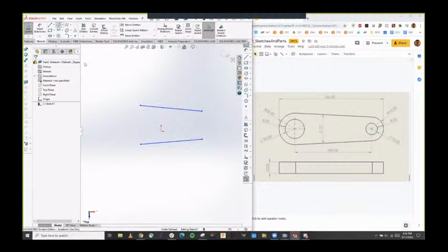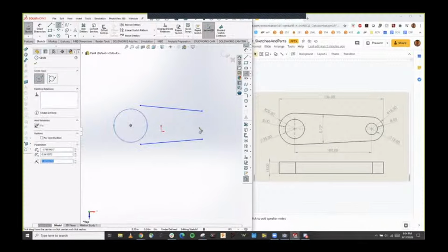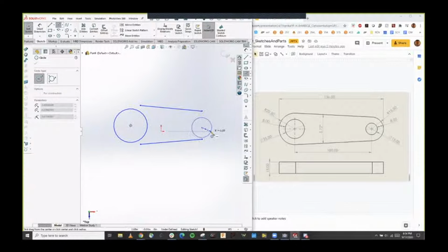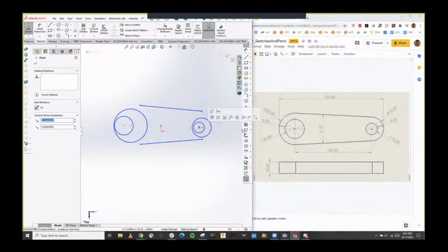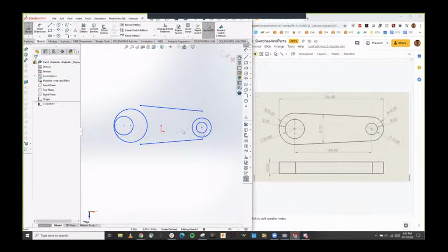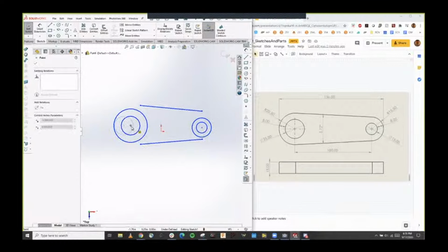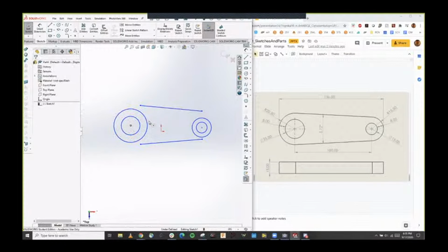Four circles, you say? Okay, we can try that. So I've generally got four circles. So we do have all the parts here. So I think what it looks like here is that these two circles, that sounded like a good suggestion. So I'll put these two to be coincident with each other, which if I just put the points together, those should form the coincident constraints there. Yep, so those are now bound together.